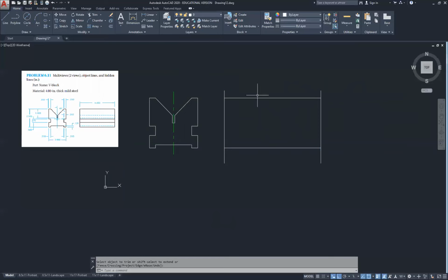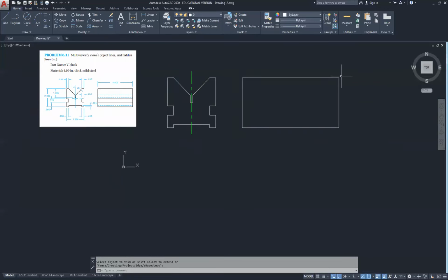Let's go ahead and get rid of any extra on the top and the bottom. Right click, repeat trim. Selecting my two cutting planes, right click, selecting that, and selecting those two. Notice that if I go past it, it gets confused on what to cut. So make sure you don't go past your cutting plane. Click enter. All right, now we have the perimeter of the side view.